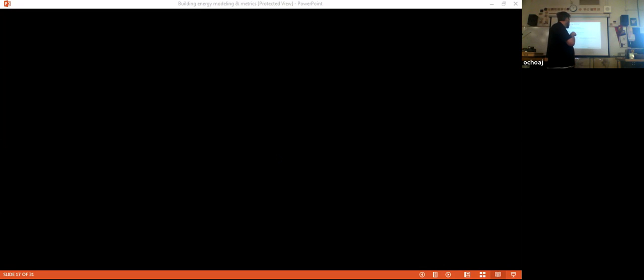Anyone want to take a chance on what an as-built is? Well, something that's right there. Yeah, you can look at the equipment that is in the building and how it performs. Yes, so that's as-built. And the term as-built, within construction engineering management, even sometimes takes an even more distinct meaning, which is that when you finish building the building, you create the as-built plans. We had plans of what we were going to build, like in a highway. They said this is going to be the highway grade. We went out and built it, but we're actually off by about 3 feet. So then we turn in the as-built, where we show what the actual highway is that we actually built. Same with the building. The windows change, the doors change. If you look in Psyche, the as-built has all that plastic stuff on the walls. That was in the as-built, not the original.